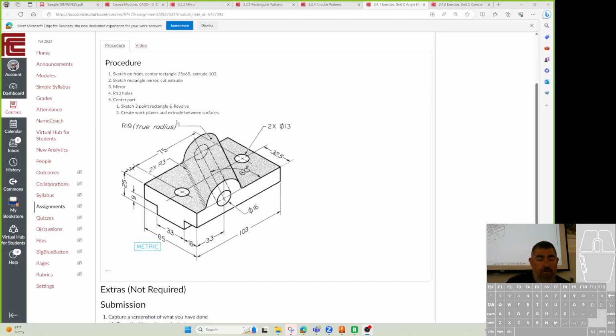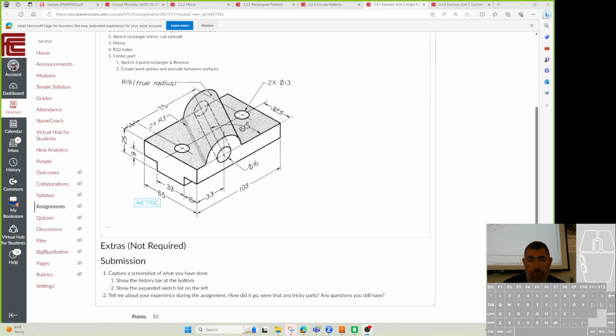All right. So if we look here, this whole piece is telling us the true radius. That's going to be the true radius when we're looking at it along its axis, not from the end, because this piece here where it's cut through isn't true. So we can't just sketch it here. We'd have to sketch some kind of ellipse, and that's not going to work.